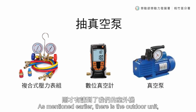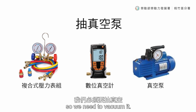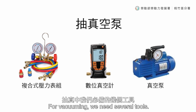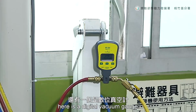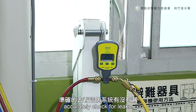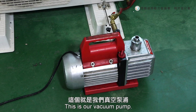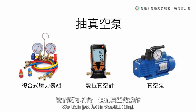As mentioned earlier, there is the outdoor unit, and during installation, air can get inside, so we need to vacuum it. For vacuuming, we need several tools. One of them is a compound pressure gauge, just like this one. Here's a digital vacuum gauge. With this, we can accurately check for leaks. This is our vacuum pump. So with these three tools, we can perform vacuuming.